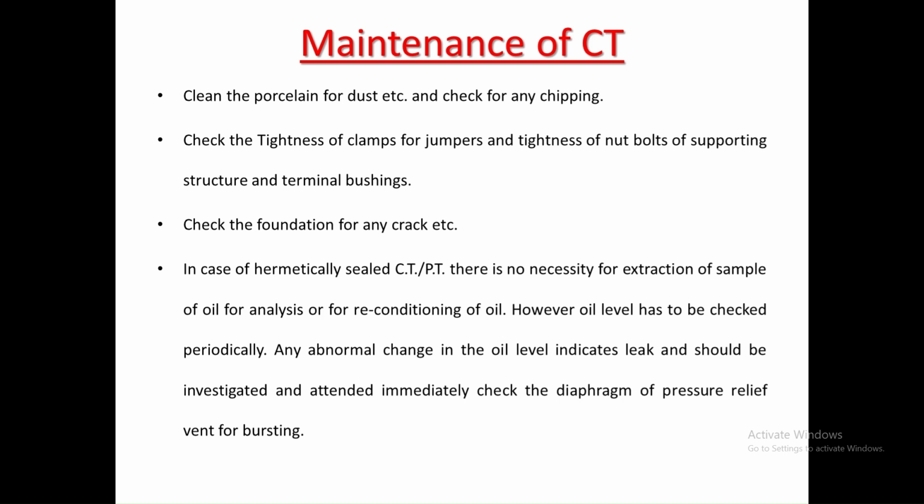Then the foundation for any crack or dysfunction, and the oil level indicator, and we should check if any abnormality is there in the oil, and whether oil leakage is present or not once it has been taken into service.